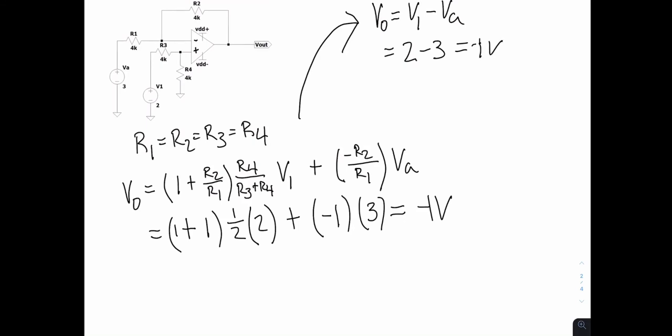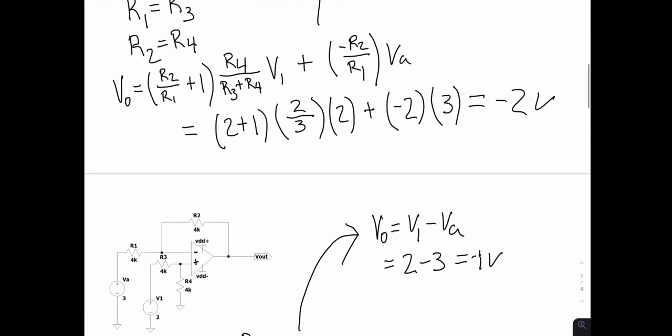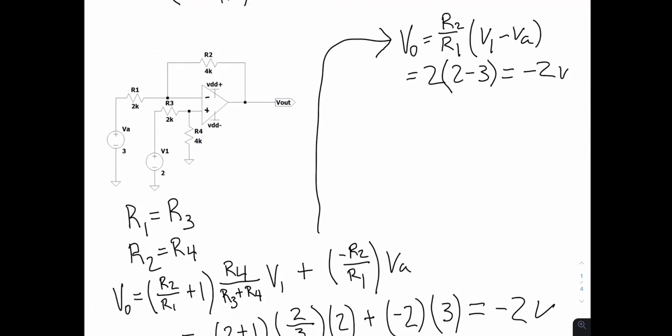This circuit is called a unity gain differential amplifier, and the voltage gain of the amplifier will be exactly 1 or unity. The previous configurations of differential amplifiers amplify the difference between two voltages. It makes this type of operational amplifier circuit a subtractor. This is unlike a summing amplifier, which adds or sums together the input voltages.